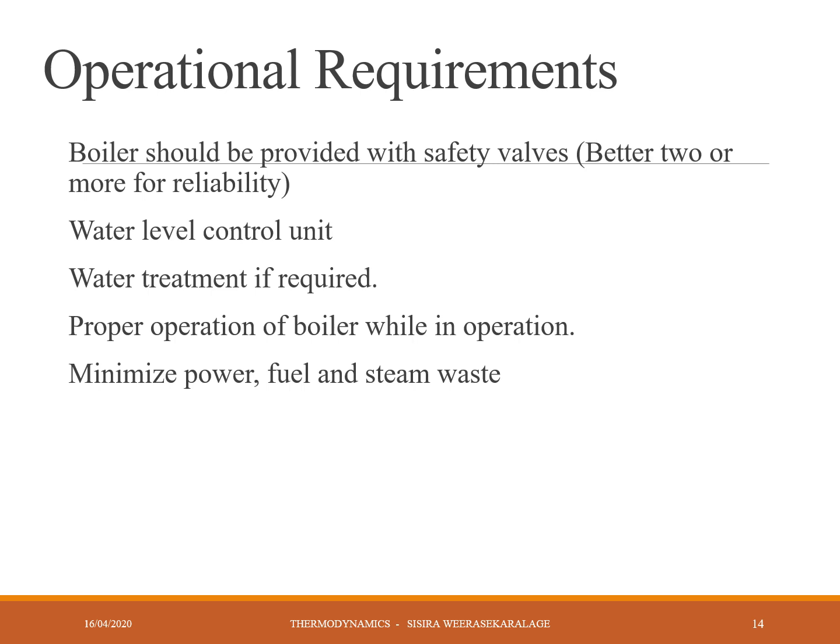Normally pressures are very high, more than 12 bars approximately. It's a high pressure, and once a blast takes place, it's worse than a big bomb blast. If it is continuously pressurizing, it's a very high danger. Therefore, the valve should open at a particular highest pressure and relieve the pressure. In order to do that, there should be an automatically operated safety valve.